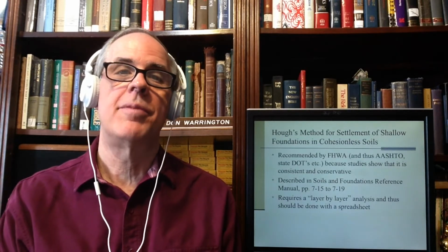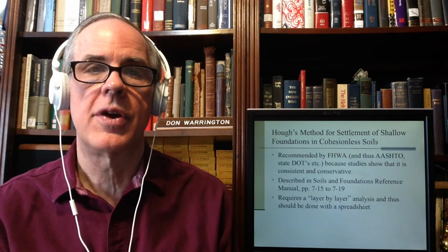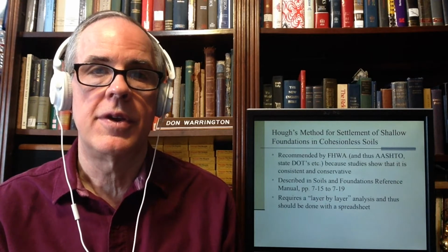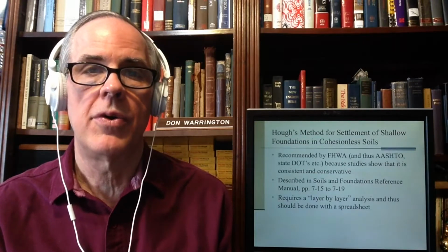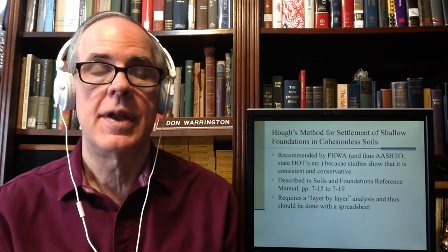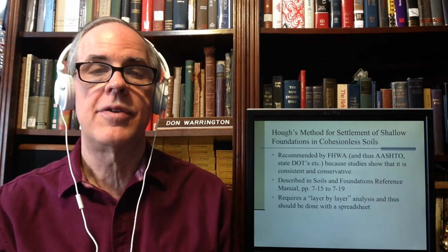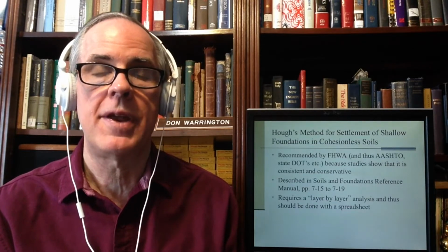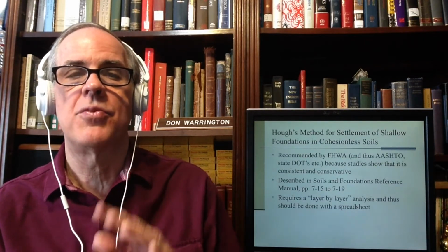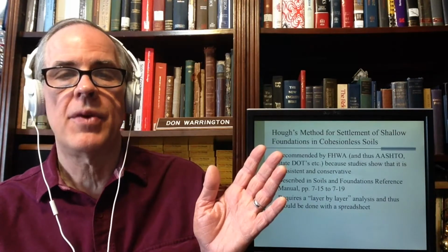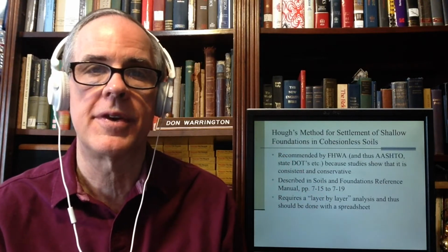By the way, as just an aside before we get into this, I'll mention the fact that back a few years ago in Geostrata, which is the Geo Institute's magazine, an article by Jean-Louis Briaud, who is now our ASCE president, discusses the settlement of the San Jacinto Monument. And when he does, he unleashes one of his pet peeves, the fact that we actually don't compute consolidation settlements the same way we use with other types of elastic settlements, with using some kind of modulus of elasticity.